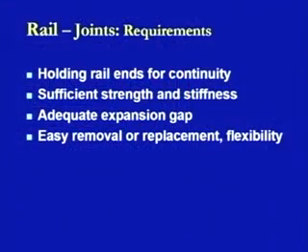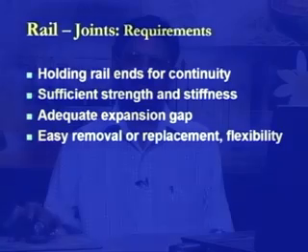The other aspect here is, because we are talking about the joints and certain fastenings have been used so as to join the two rail sections as well as join the rail sections below, one thing to be taken care of is easy removal or replacement of the different components or materials. Now, at the section where the joint is being provided, most of the time there may or may not be a support being provided. In Indian conditions, we are providing joints which are not being supported. So, in that case, it is being supported by the ballast cushion which is placed around the sleepers or below the sleepers. If we have to remove this material, then it should be easy to do that, or if we have to replace it, then that should also be easier. At the same time, the flexibility should be there so that as and when it is required, that work can be done from the maintenance point of view.